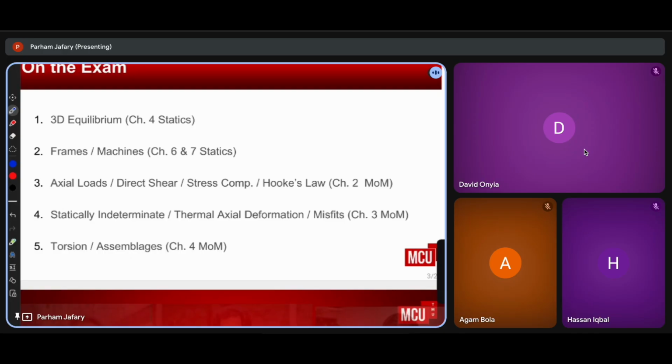Okay? So I would write sigma M around AD is equal to 0. And then I have to come up with the vectors for AD and the connecting vectors relative from point B to the axis AD. Okay? So AD itself is i hat minus 0.75 k hat.